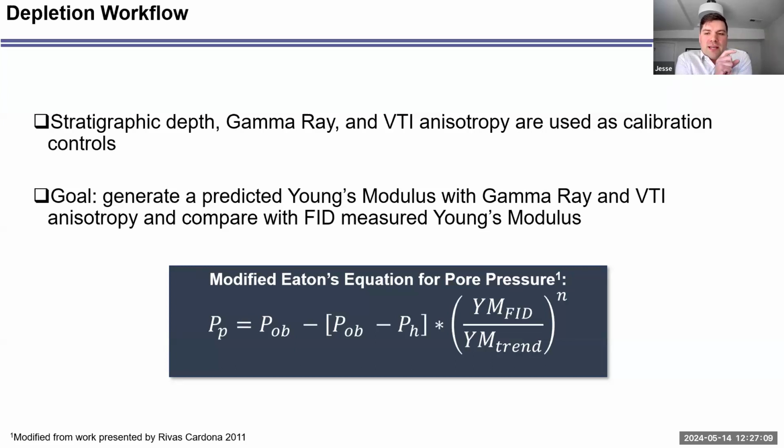And so we take that estimated Young's modulus value and we compare it to our measured Young's modulus value. Part of this started out with just field operations, but if you dig into the rock mechanics literature, once you go beyond the effective stress that a rock has seen, you start to see a rapid change in the mechanical properties of the rock.